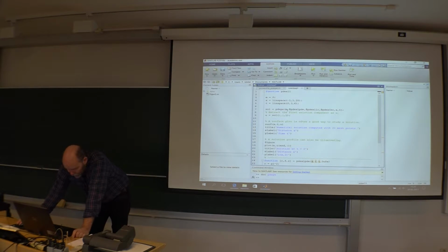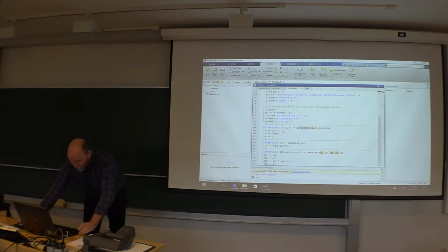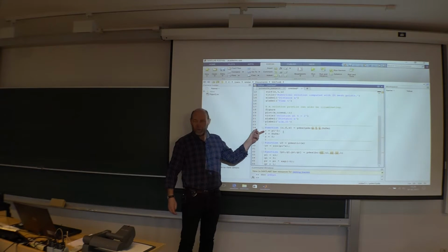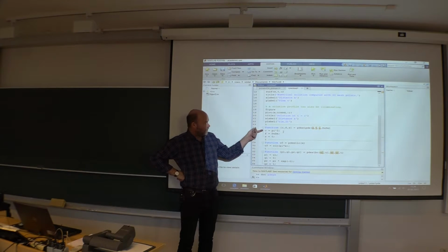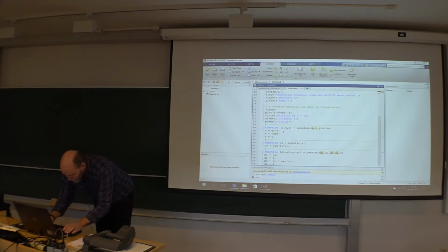Then we have to address the coefficients in the equation first. This m is set to be 0, that's quite okay. And then the first function decides how your equation actually looks. So here you specify the coefficients, if you remember from the documentation. Coefficient c, in our example, is just 1.